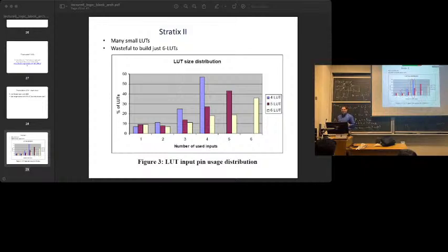You might go, what the heck are you doing with a 1 input lookup table? It's usually between registers, for example. You're just going through the lookup table to get to the register, which does happen sometimes. I have a shift register, there's really nothing for the LUT to do. It's just going to pass the data through to the flip-flop.